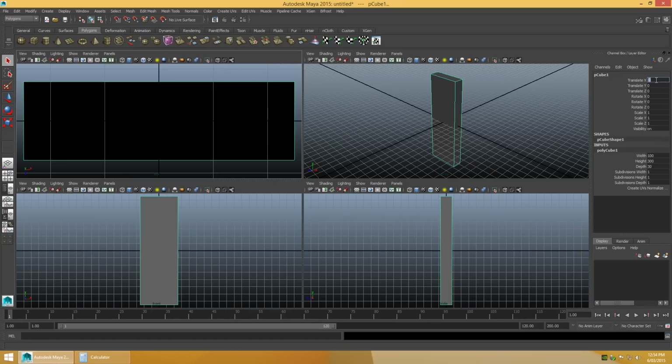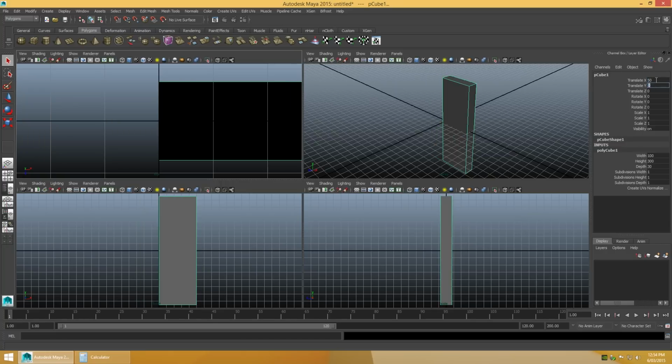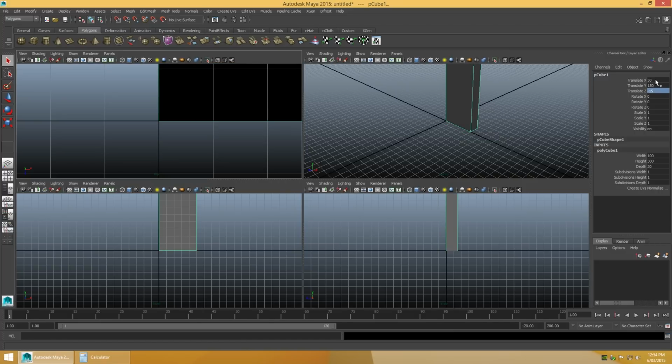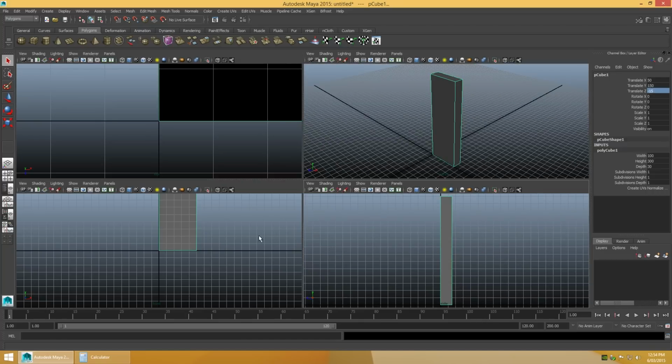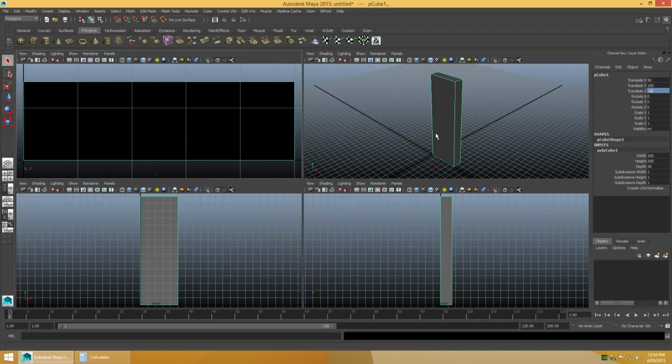An important consideration with modular meshes is the pivot point. When importing a mesh into the Unreal Engine, it ignores the pivot point set by Maya and instead places the pivot point at the origin, which is equivalent to the coordinates 0x, 0y, and 0z. Due to this, you'll need to offset your mesh to achieve your preferred pivot point location. For architectural meshes, I prefer the pivot point to be located at the front left.